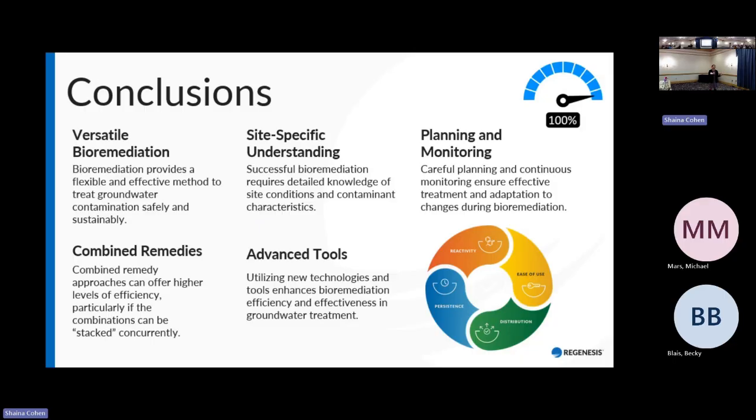Then on the analytical side, certainly the contaminants of concern are also huge. What I see sometimes being an issue, and this varies state by state on what is regulated, is that in a lot of states they're mostly concerned just with the VOCs and SVOCs and not necessarily the total petroleum hydrocarbons, even though depending on how weathered the plume is, that might really be the predominant mass of some of these non-specifically analyzed VOCs making up the overall demand. So getting a really good picture of that can be really helpful, before and after.